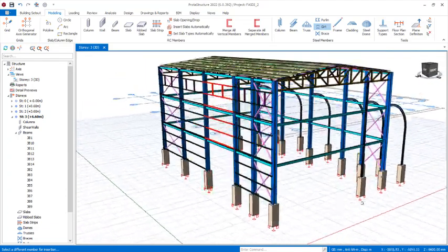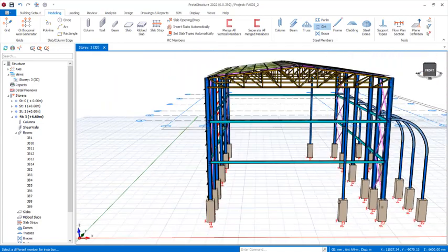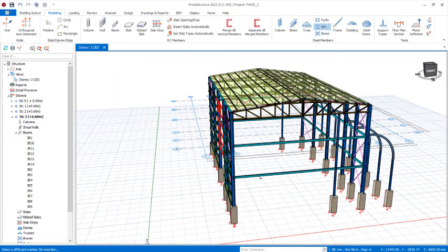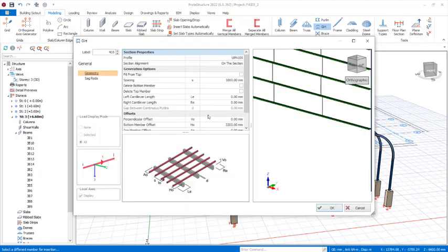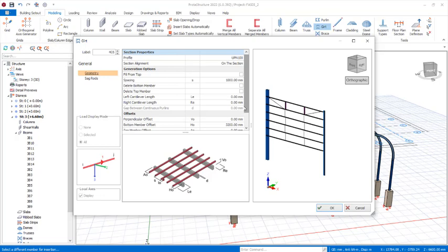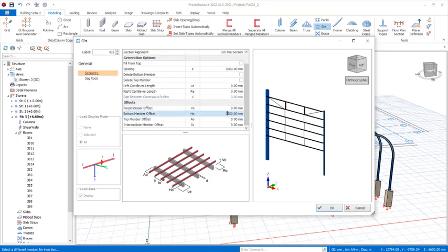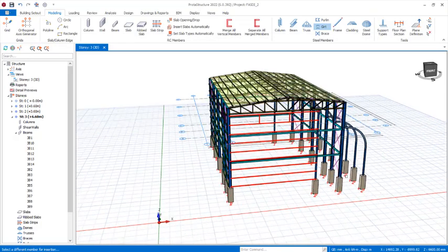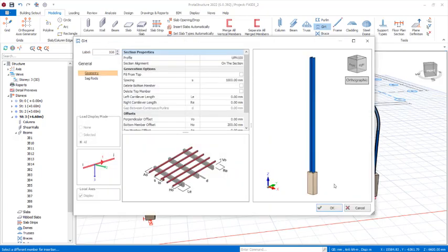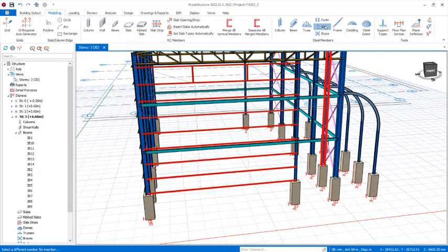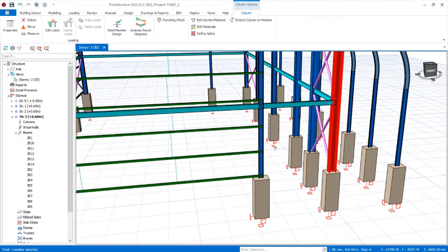All right, so over here we'll also be having these small provisions as an entrance, so we'll be placing a gate here as well. So pick these columns right there and then pick this one right there. So you have this with that offset that you have inputted. So at this time we are going to remove the offset, change it to 200. Get it like this, just 200 right there. Click on the OK options to have it just like this. So for this provision now, select this, select the gate, and then pick this column and then this one.